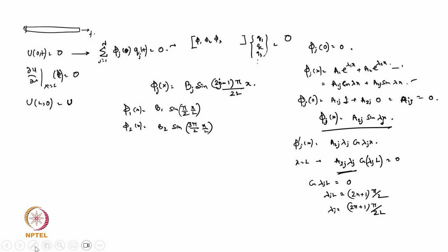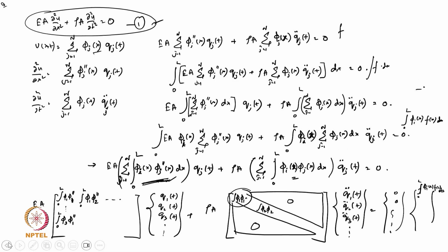Now there is one interesting point that I should also mention: if your excitation is not purely harmonic, for example if you are solving for a time response, then you can understand that the first method, where we make the spectral element, or directly assume the harmonic solutions and make the shape functions frequency dependent, is not that suitable, because you may not want frequency dependent shape functions.